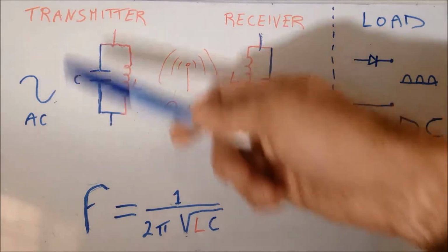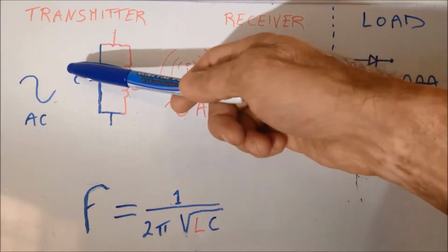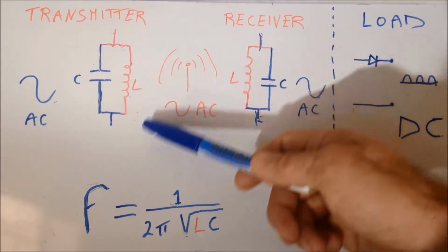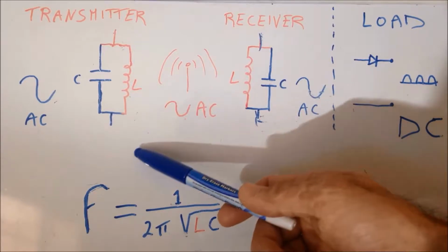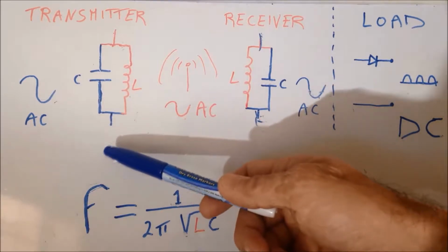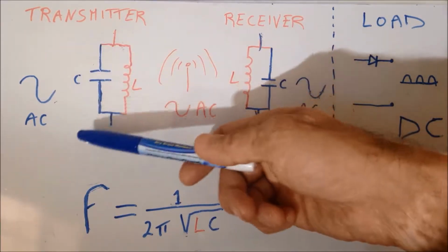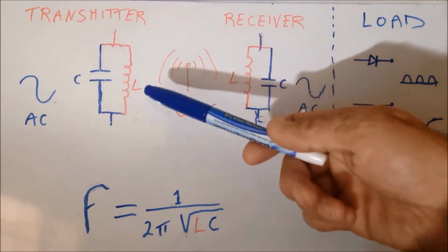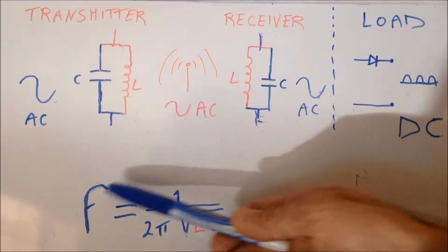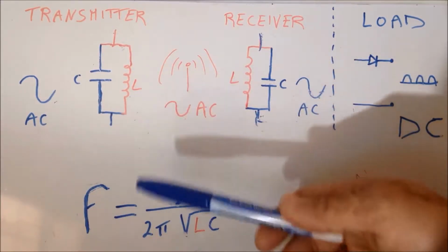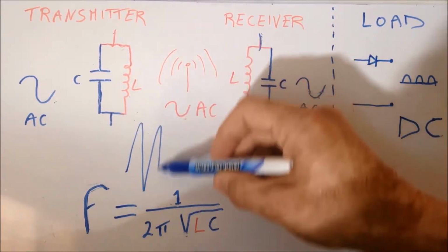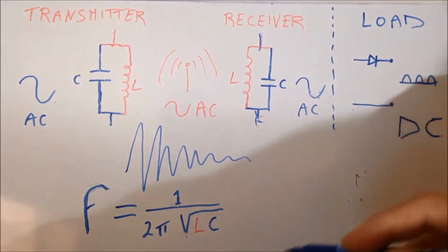Once you apply the charge to the capacitance, the capacitance is going to discharge all the energy into the inductance. The inductance finally creates a magnetic field around it that creates also an equal and opposite charge to our capacitance, which will eventually recharge and discharge in an endless loop. Well, endless loop is a little bit too much, since we know that a perfect capacitance and a perfect inductance don't really exist. So all the energy is going to get lost in a classic resonance waveform.